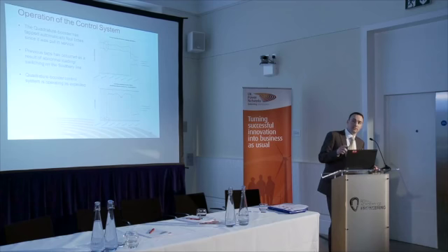Maybe what isn't so evident from this, though, is that the Sudbury circuit isn't actually carrying a lot of load. It's almost negligible load. And that's the main reason for the quad booster tapping in this scenario: the Sudbury circuit isn't carrying any load, and the Downham Market and Needham Market are carrying more load than what we would normally expect them to.